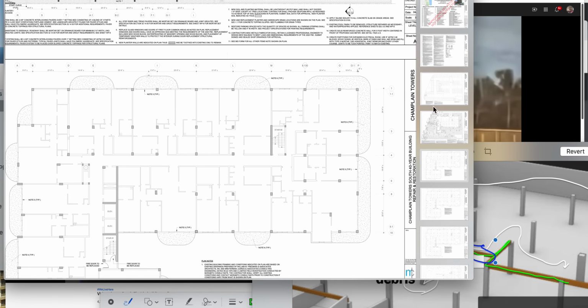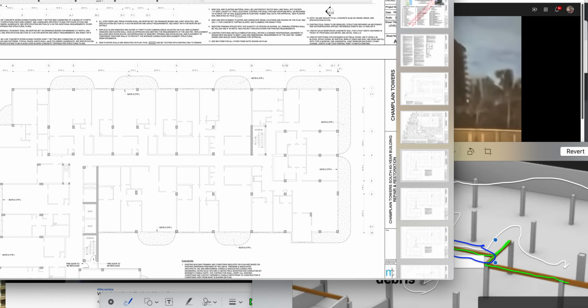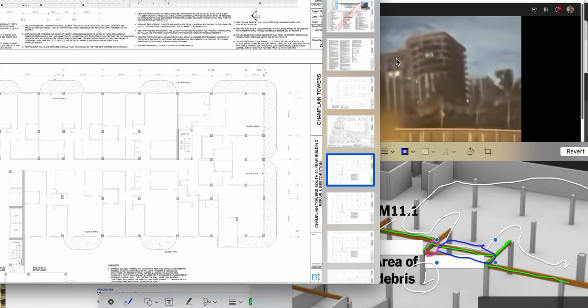Oh, the flapping. How you see it flap so easily down the rotation there. We have a break from here to here, which is a corridor. You see there's the span of the concrete. As this goes, it's going to make an easy flap. And then the puncturing happens there, or buckling happens to the internal columns. And we make it back to right about, somewhere about here is our rotation. This might be our rotation point that we're looking at already, or it might be right about here, the rotation point inside the video.